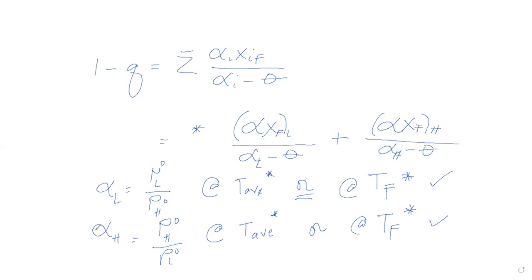Or another option is finding the alpha using Fenske's method that is explained in the sample problem I also placed in this slide. The determination of alpha using Fenske's equation is in the slide, or you could use that one. So you have three options in finding the alpha. Either based here, or based on Fenske's equation, which does not need the temperature. All it needs is just the mole fraction of the components in your mixture.